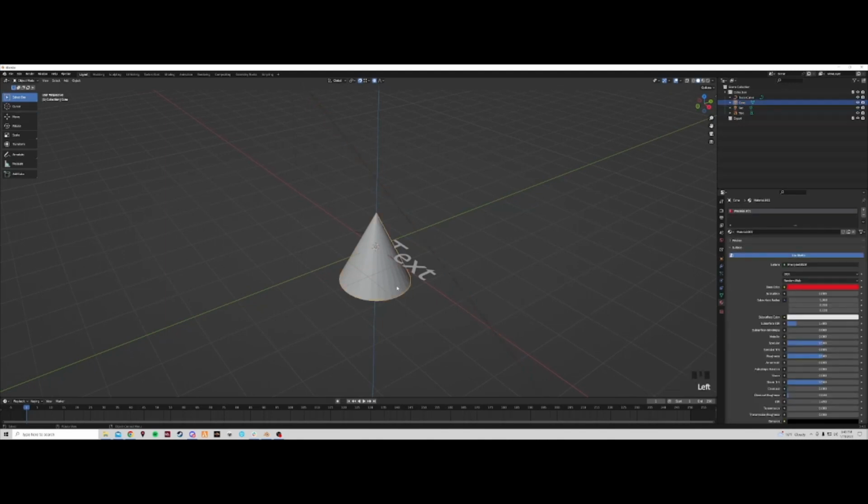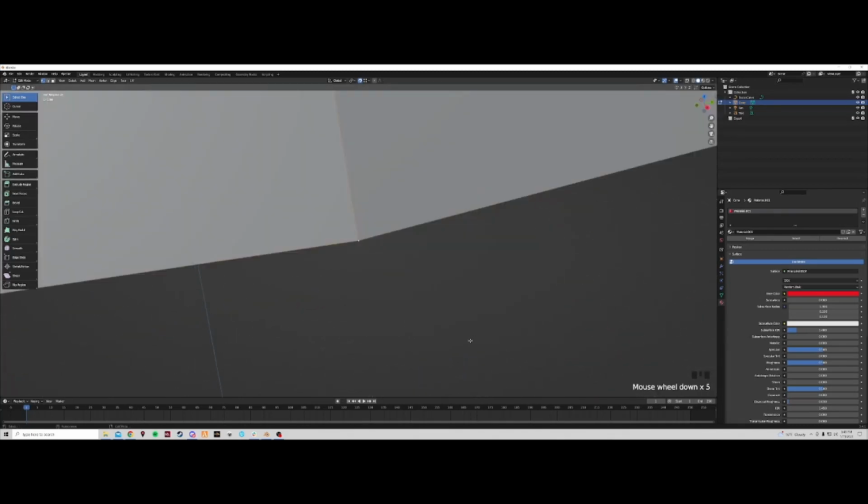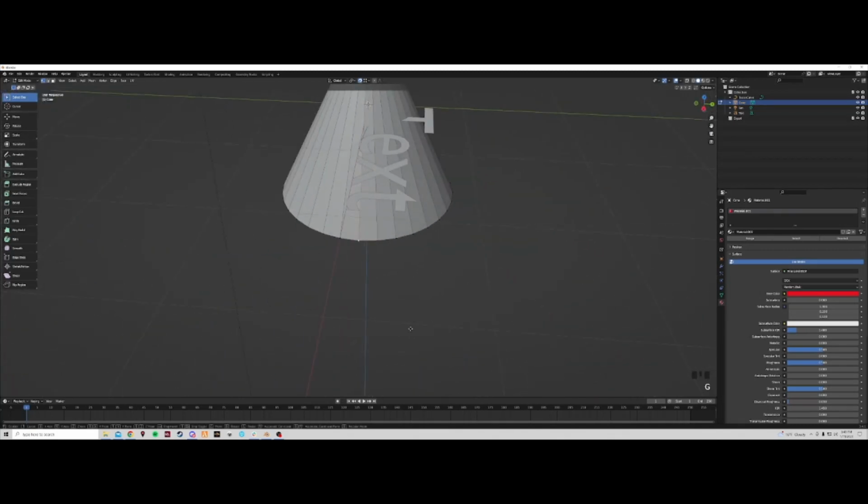Versus square, you can kind of see how they affect, but I'll show you how they actually work. So with this object selected and in edit mode, if I select this one vertex and I go to move this one vertex, you can see right now it's moving by itself. If I turn on proportional editing with the smooth option set, it will smoothly move things within this circle.